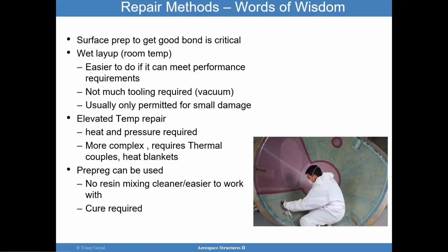The surface prep is important to get a good bond, and it's critical. A wet layup at room temperature is easier to do if you can meet the performance requirements. It doesn't require a lot of tooling, and is usually used on small damage. Elevated temperature repair requires heat and pressure.